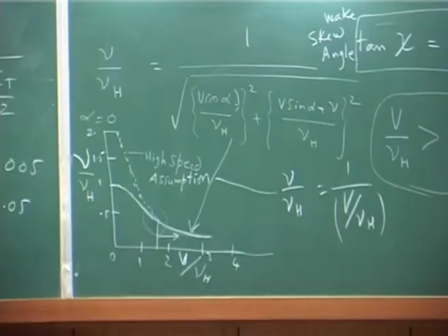That corresponds to, if you take lambda h as root of Ct by 2, so V over nu h you can non-dimensionalize as mu over lambda h. It is greater than 0.075 precisely, but you normally take greater than 0.1. 0 to 0.1 forward speed, which is the advance ratio, forward speed divided by tip speed. If it is in the range of 0 to 0.1, you say that is transition.